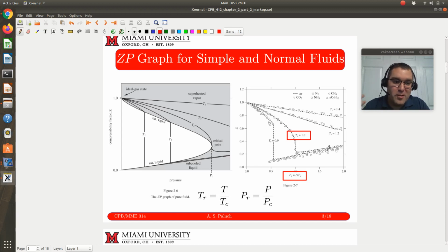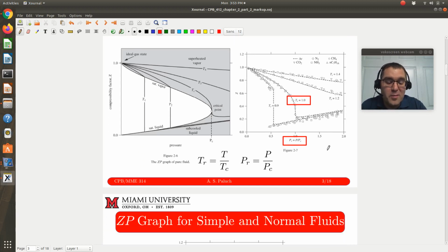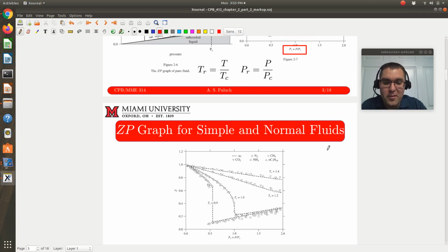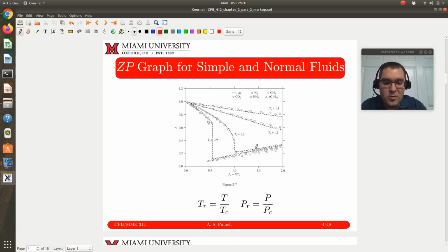This is the idea, and it works okay for what we'd call these simple molecules. But there's definitely deviation. You can see the spread; the agreement isn't perfect. But the first key takeaway is the idea of corresponding states theory: when I plot in reduced coordinates, I can get data collapse. This is huge and significant for design applications, in terms of minimizing the amount of data that would otherwise need to be collected or tabulated to go through these design schemes of comparing, say, different refrigerants, different fluids. But it's not perfect.